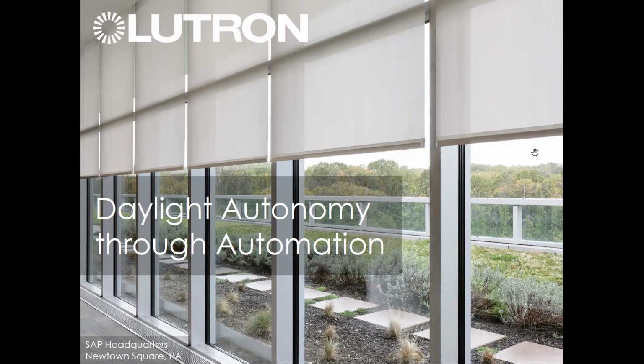First things first, we're going to be talking a little bit about shade automation and daylighting control, and we're going to explore its impact on daylight autonomy. The purpose of daylight autonomy is really to maximize the useful daylight to limit the need for electric lighting in a building. So in order to do this, we need to consider how daylight impacts the occupants of a space, both positive and negative. And in this presentation, we're going to show how the best way to properly design for daylight is to use dynamic systems, or systems that will adapt based on daylight conditions to optimize for energy and/or comfort.